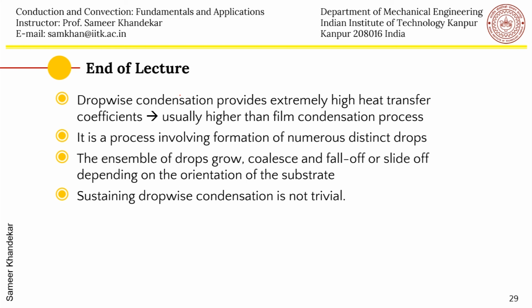So in large industrial sectors, it is mostly film-wise, because after a period of time the hydrophobicity of the substance deteriorates, and the physical morphology or the chemical coating which you have done to enhance dropwise condensation is not sustainable, and therefore you go back to film-wise condensation.